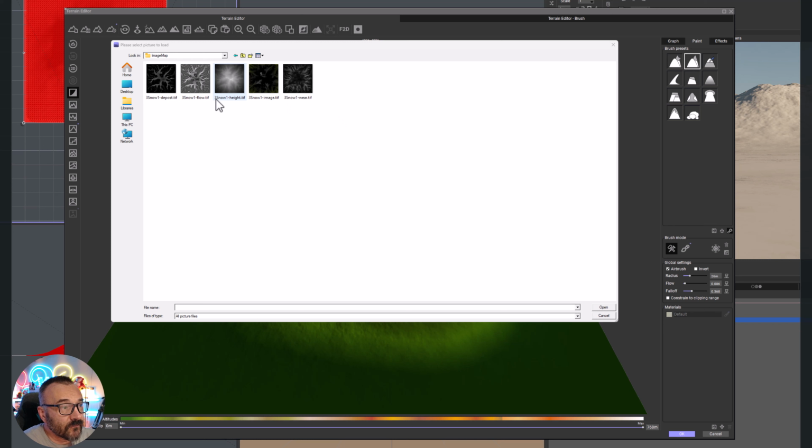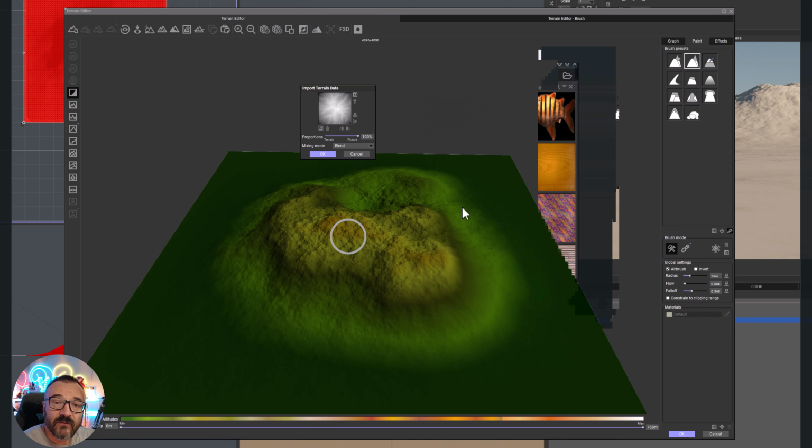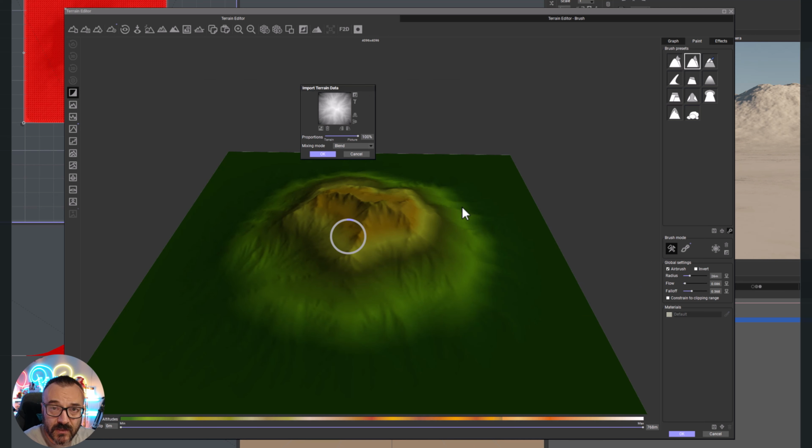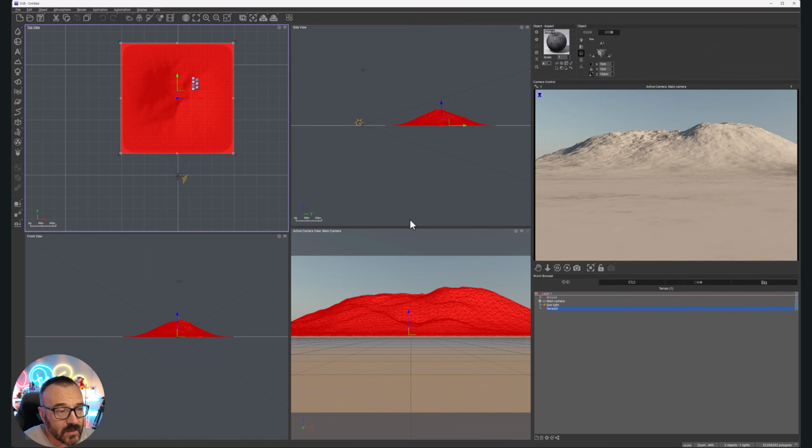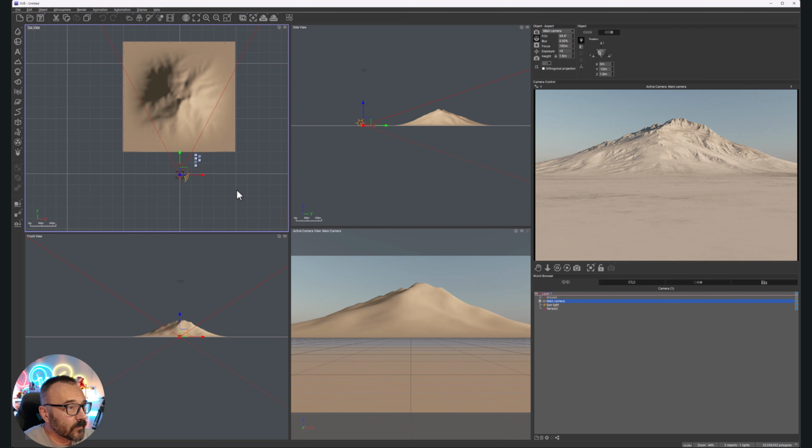We're going to select the first, which says height-field. Let's click OK, and notice that the file was in a TIFF format. I highly recommend not using JPEG due to compression, because then you will also see pixelization or dots on your terrain. As we're loading, we want to be sure our picture is at 100%. On this 100%, we want to set it to blend, and you can see it already has a very beautiful look. Let's click OK, and click OK one more time. So notice we have a very beautiful look.